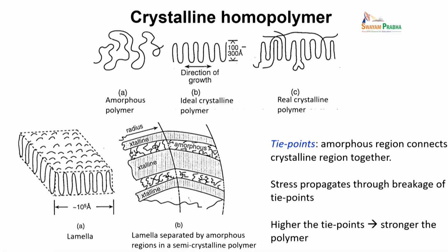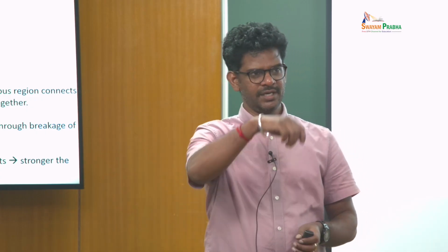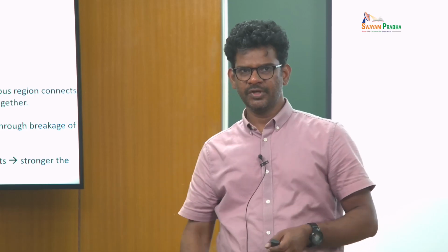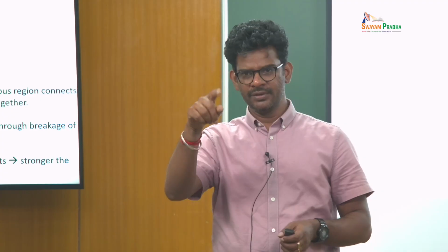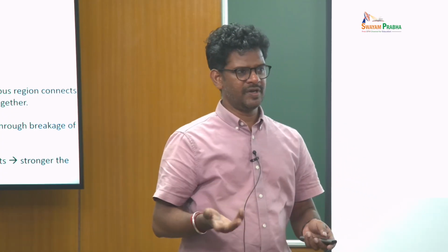What you generally have is a polymer where, on average, there is some order, but there are also a lot of defects. There are chains that are making an extra loop here, right, and sometimes this one is not participating further, and another chain is taking part in the repeating units, okay. So this looping structure of the chains over and above is very typical of a polymer crystal.